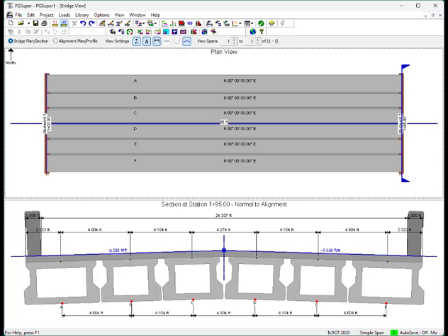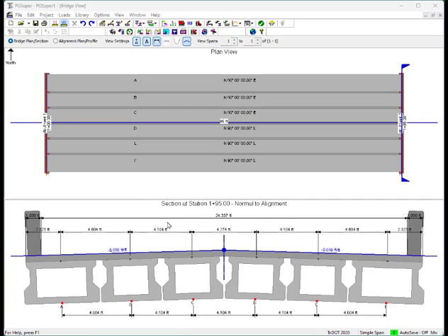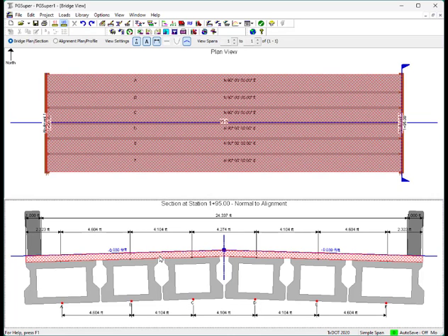Next, let's explore some of the more spacing options for box beams. And I'd like to note that slab beams behave in much the same manner. Over the years, we've had several engineers ask us to allow overhangs on adjacent box beam bridges. So let's see what it takes to do this. And I'd also like to note the spacings here of the exterior girders is about 4.6 feet, and the interior girders are about 4.1 feet.